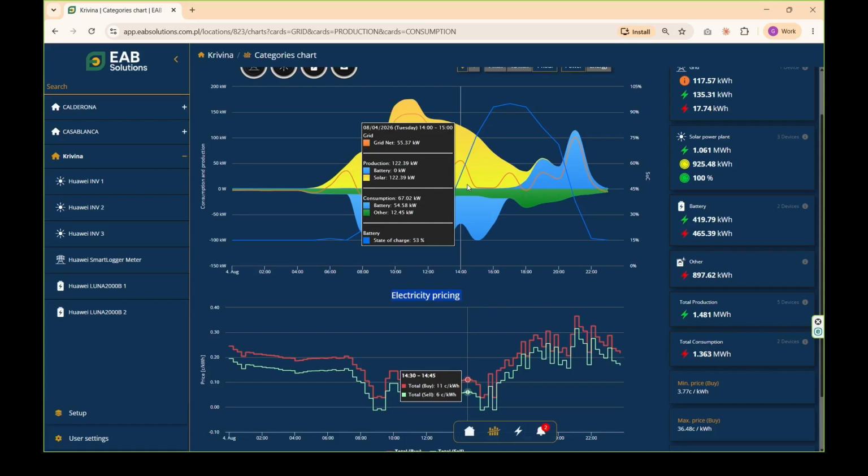It doesn't matter if the PV isn't working. We'd keep reading electricity prices, charging when it's cheap, discharging when it's expensive, and generating return for our client. And the same with power peaks. If the client is going to draw an excess of X power at a given moment, and that exceeds the contracted power, our battery, which has energy, would cover that excess to stop us drawing more than the contracted power, protecting our client.